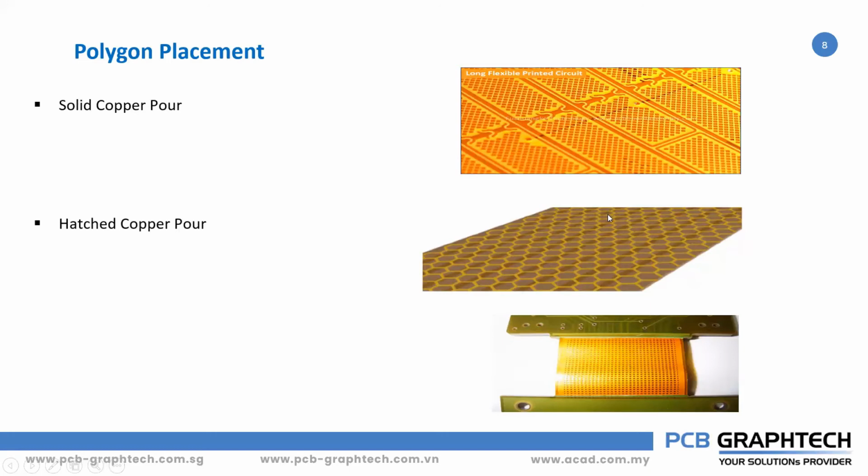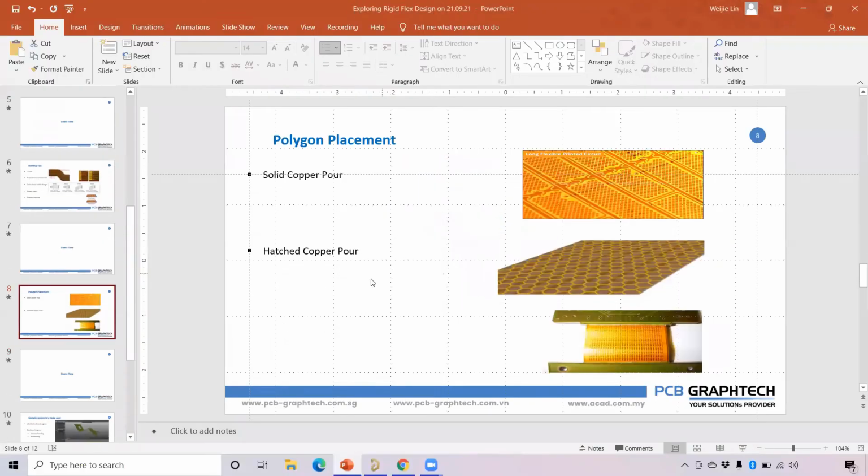So normally, as I told you, when you use solid copper, it will break. Here, when you use this hatched copper, the advantage is that copper is only at certain lines. The remaining areas, it will remove the copper, and it will flow only along those particular 45 degree lines. So it will reduce the copper amount inside the design. We will see inside the software how it works.